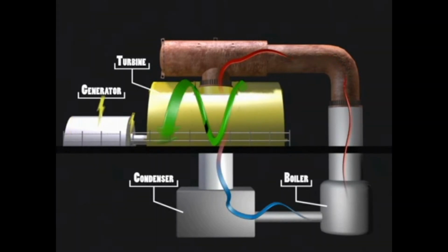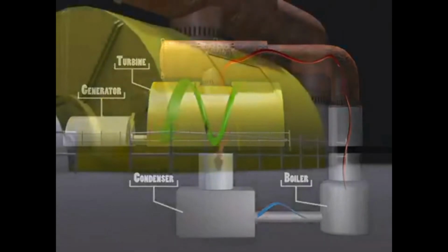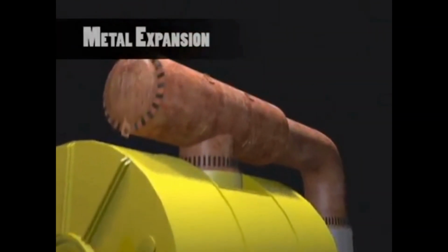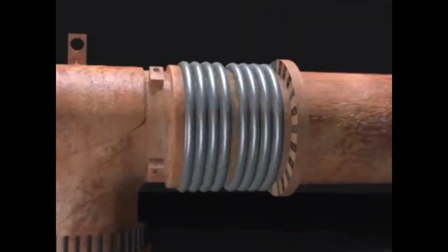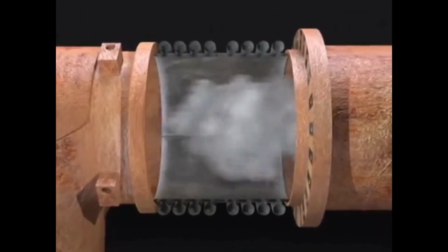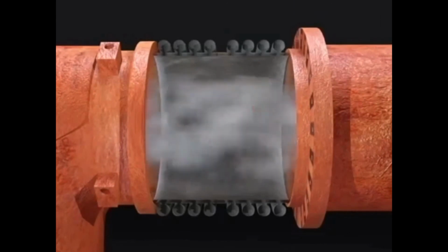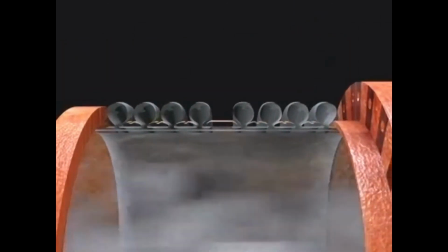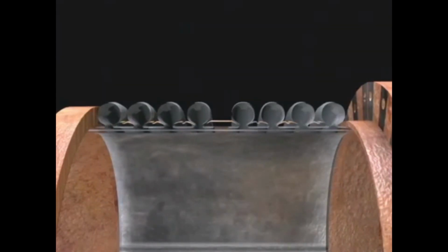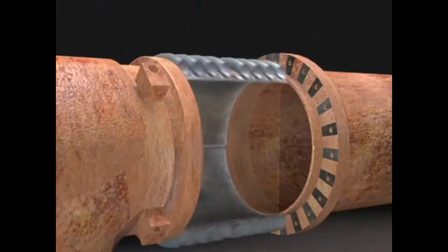When metal becomes hot, it expands, which without an expansion joint would cause the pipe to break off of its position. The bellows is a piece of flexible metal that, when the metal pipe begins to expand, will compress on itself, alleviating the stress on the turbine. In the boiler, when the pipes pull down, the bellows return to the original position.